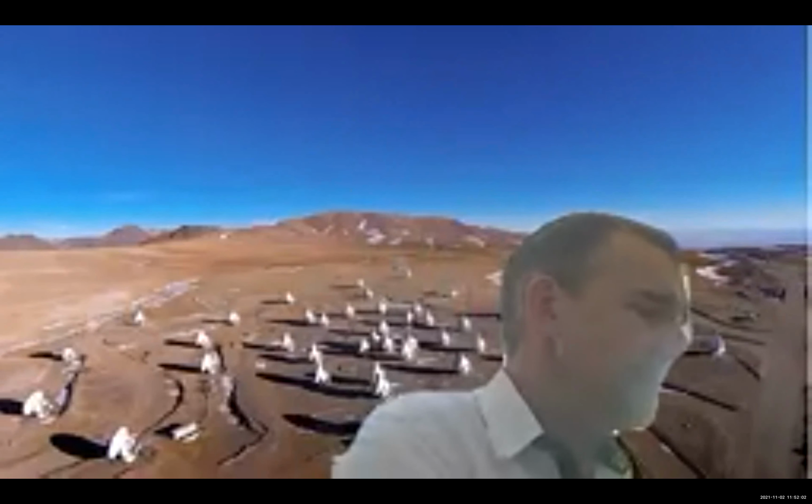This is Crystal Brogan. Maybe I can answer with a little bit more context. Basically, if what you want is continuum sensitivity, then you can get that by making a really wide bandwidth, which people are working on. And sometimes it's best to do that with double sideband, because even though you're taking a big noise penalty, if you can make the bandwidth wide enough, you can get that sensitivity back if you're interested in continuum science. However, ALMA is extremely interested also in spectral line science, and there is simply no way to make a double sideband receiver that preserves really high spectral sensitivity.